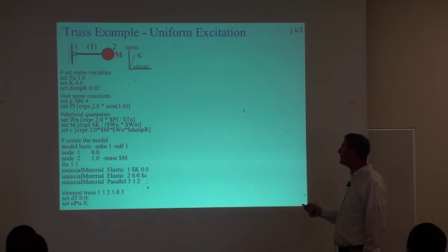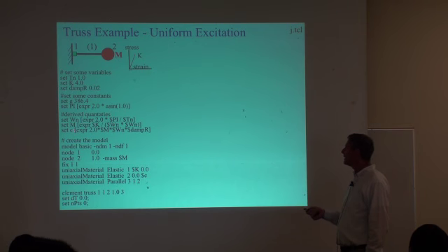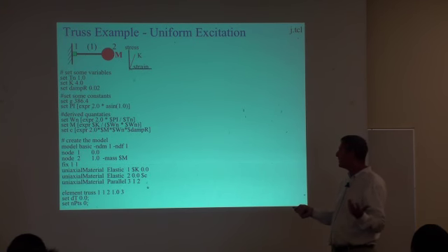Okay, so I'm setting a period, some stiffness and a damping ratio; I want 2% damping. I set some constants, the gravitational constant and pi. Based on these quantities, I derive what my mass should be. Then after I figure out what all these derived quantities are going to be based on my input,